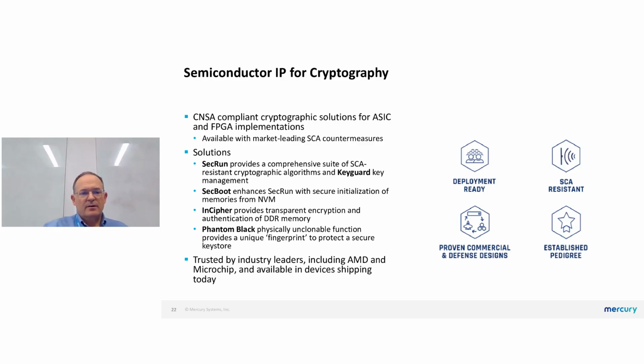And this can transparently encrypt the DDR memory that the operating environment operates out of. Encipher includes both leakage reduction and protocol countermeasures for side channel attack resistance. So this is really a comprehensive capability that does not cause a functional change in the operating environment for protecting that data that needs to be stored in that large bulk memory.